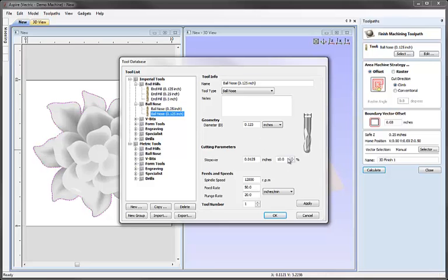There are some other important parameters within the tool settings here, particularly when we come to do finishing, and one of those is the step over. At the moment we have this set to 10% of the tool diameter, or an actual distance of 0.0125 of an inch. What the step over refers to is the distance the tool is going to move over between each pass of the toolpath. The way the finishing works is to move along in a straight line, and then at the end of that straight line to move over a little bit and come back over the 3D object, step over again, come back over the 3D object, and that's how the part's replicated.